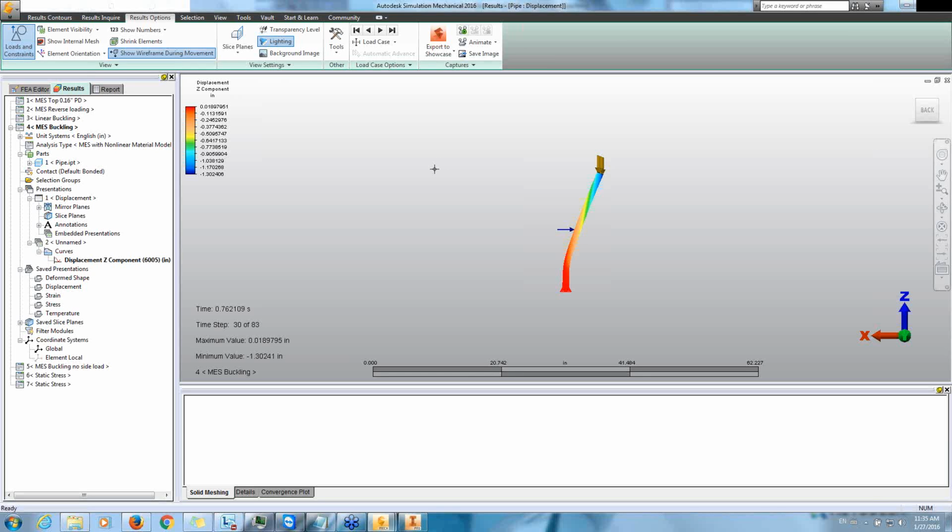Let's say one component of the structure buckles, but the rest of the structure is going to catch it, though obviously it's going to experience higher stresses. So you want to look at that case and say, okay, can I live with that? Or it's okay for now, but I need to do something about it, or I can forget about it. So you might want to look at that.